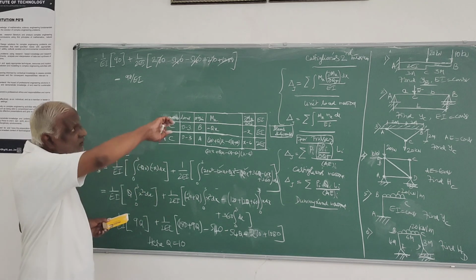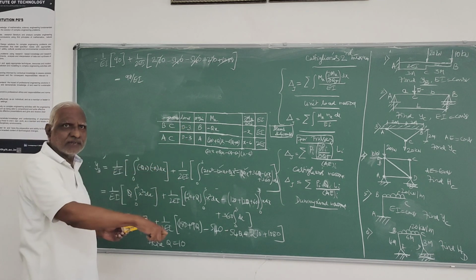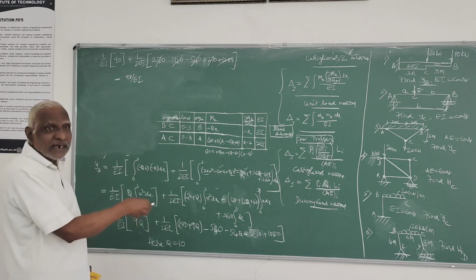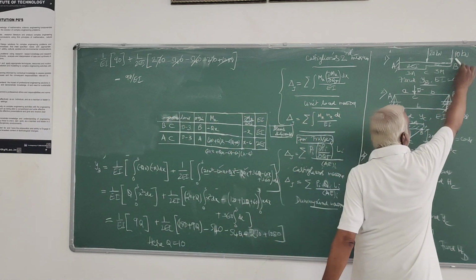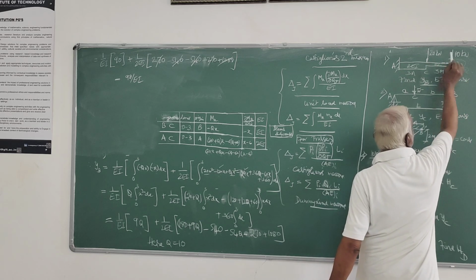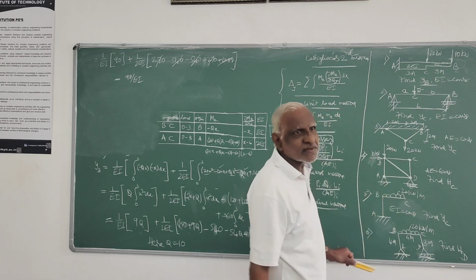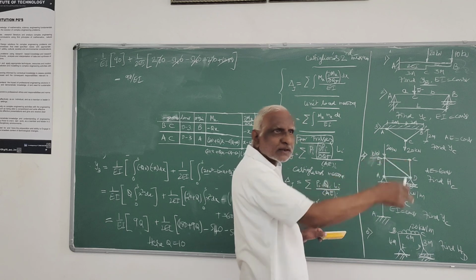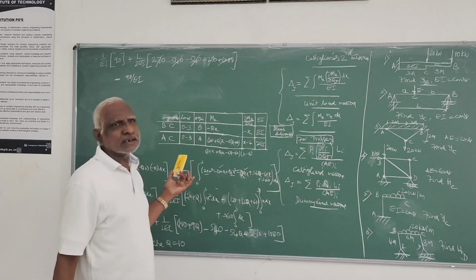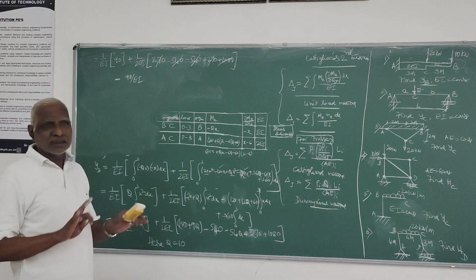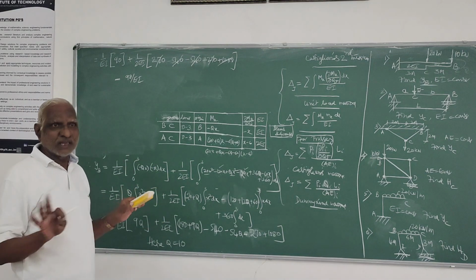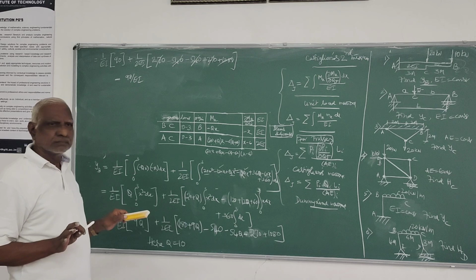And if slope is asked, instead of vertical deflection, you have to apply a moment load, Q. Q will be a moment. You have to apply Q like that. Then you retain the 20 and 10 as they are, and the moment Q also you have to take into consideration for finding the reaction as well as Mx. That's all the change.